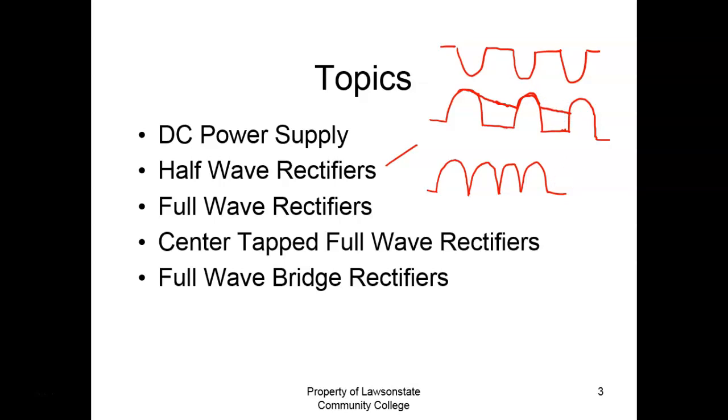You can't see what I'm doing. Yeah. So what that means is if this was AC, the thing that I charge up would have to handle the load for 16.7 milliseconds. Over here, it would only have to handle the load for 8.3 milliseconds.